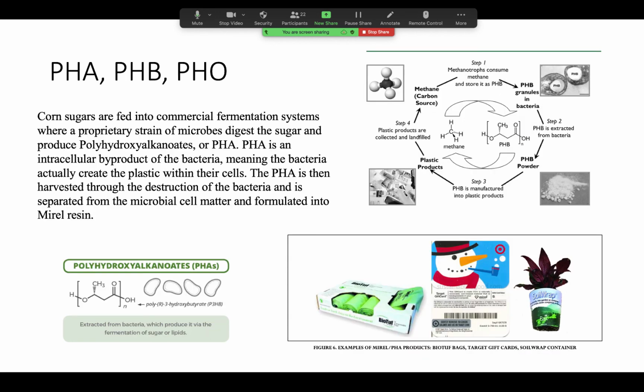Another one that is fairly widely used is your polyhydroxyalkanoates, or PHA. This one I think is pretty cool because it's built up in bacteria. So bacteria are engineered to produce high amounts of this PHB inside of the bacteria, and then they're destroyed and they extract out all these starting materials, this PHB, and then it can be polymerized and you can make it into your products, which then will degrade themselves. Right, those are some examples we have here.